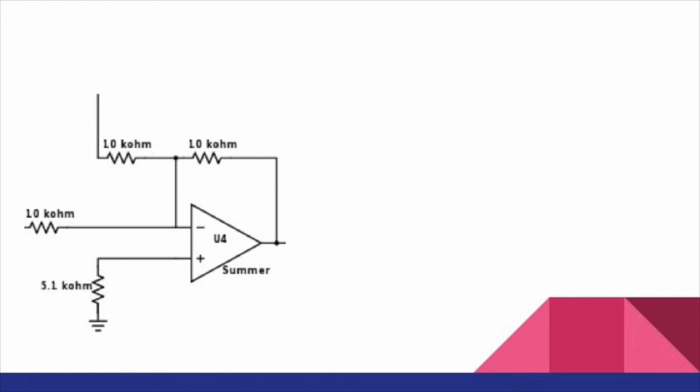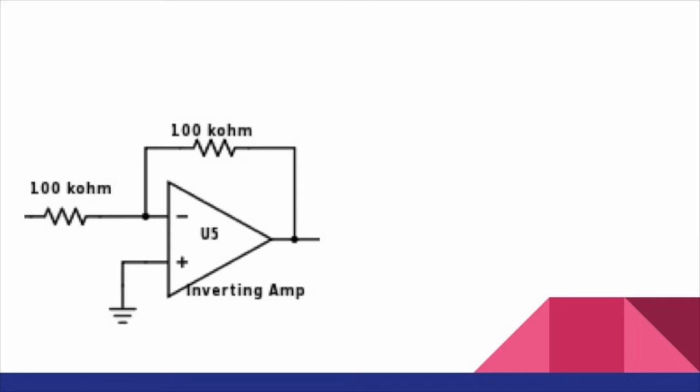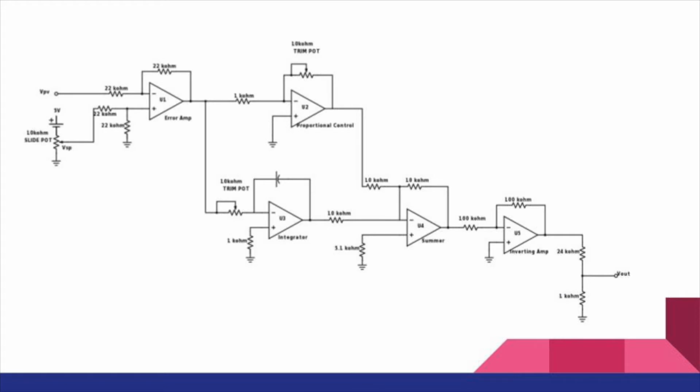The combined voltage is then inverted with an inverting amplifier to produce a positive corrective action value. A voltage divider is placed after the newly inverted voltage to achieve the appropriate voltage for the final control element.